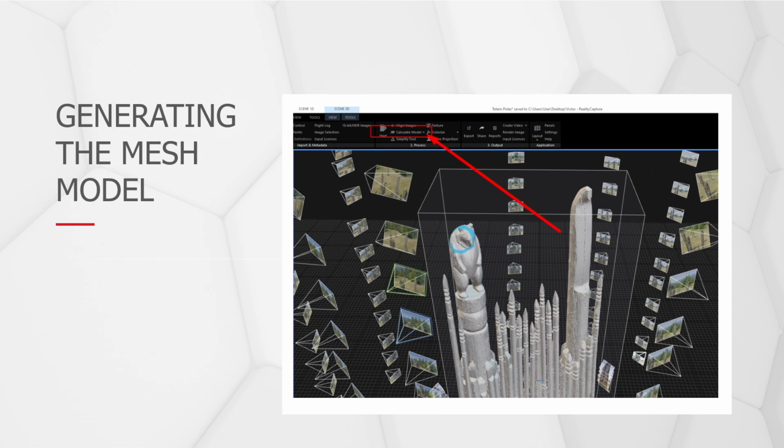Now this is also another step where you want to zoom in on your 3D structure, look around, and look for anything odd in the meshing. Sometimes the point cloud gets confused and it'll try to mesh points that don't make sense. So you want to have a close look at it and clean up any issues here. If you go ahead to the next step with texturing, you're just going to ruin the overall photorealism. Right, so making sure we have no gaps.